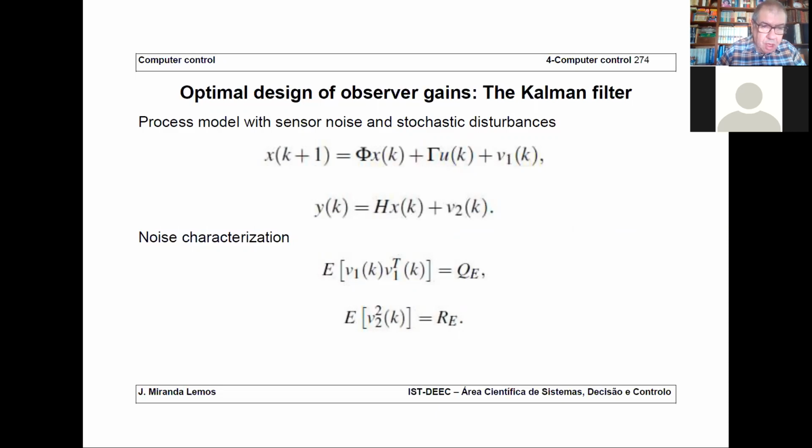Now, if you have some band, you are letting interesting components of X in that frequency range pass, as well as noise. Now, go on enlarging the bandwidth of your filter. There is a point at which all the useful components of X have passed. X is typically a low pass signal, so there is a frequency value after which all of the components of X go across the filter and are not attenuated by it. And if you enlarge it more, you are not letting more X pass, but you still have noise passing, because noise is a white noise.